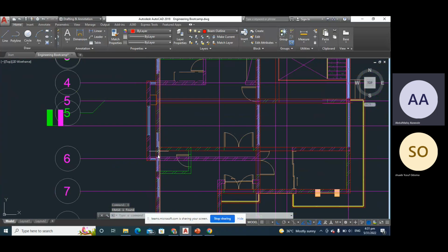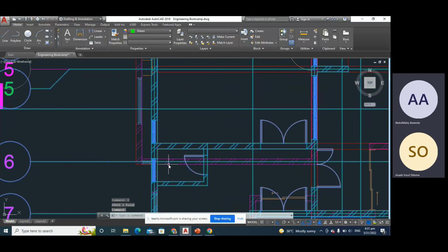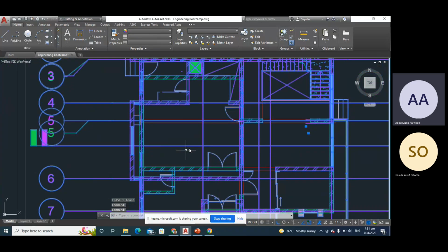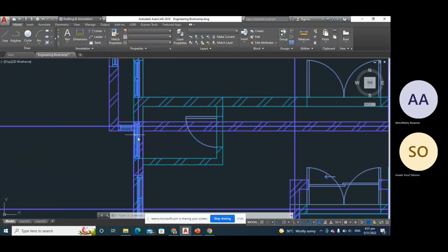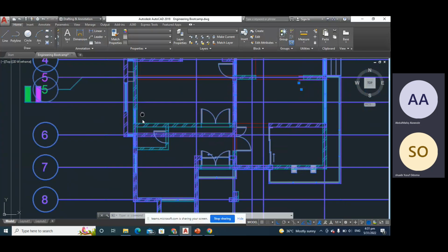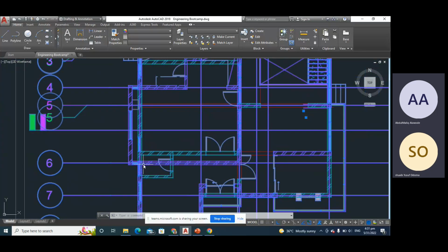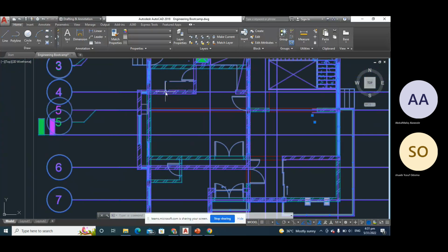I have this place as a slab, but I've seen something here. If I highlight my ground floor and my first floor, this junction and this junction is a common point both on the first floor and on the ground floor. So I can decide to have a column here and here, such that when I get to my roof general arrangement, I can extend a beam over them to this area and extend another beam over there. So that beam is just going to be a cantilever on the column here, and this beam here will be a cantilever on the column here.